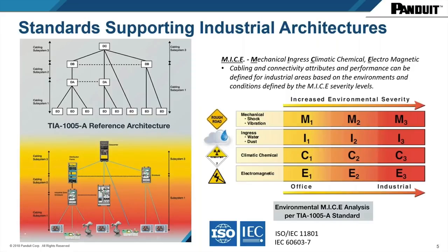So the edge devices and factory systems are exposed to extreme conditions, and it is not always the case. So if you go to a robotic cell, for instance, there's a constant flexing that takes place at the mechanical device. So cabling that's connected between an edge sensor on the robotic arm to its base, that cable connection point is taking a lot of abuse over time. And that changes the environmental severity that needs to be applied in that instance.